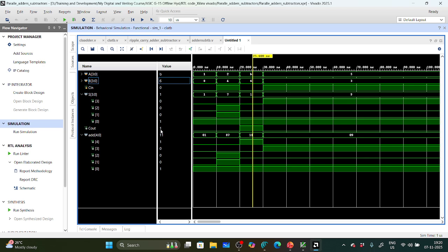So in these two cases, you are not getting carry out. Carry out equal to 0 only. In this case, you are getting carry out equal to 1. Why? Because my number is 0, 0, so 1 triple 0 1. Triple 0 1 is 4 bits only, that is given to sum, and carry out equal to 1. That is 18 you are getting. If you convert 18 to hexadecimal, that is 11. You are getting 11.